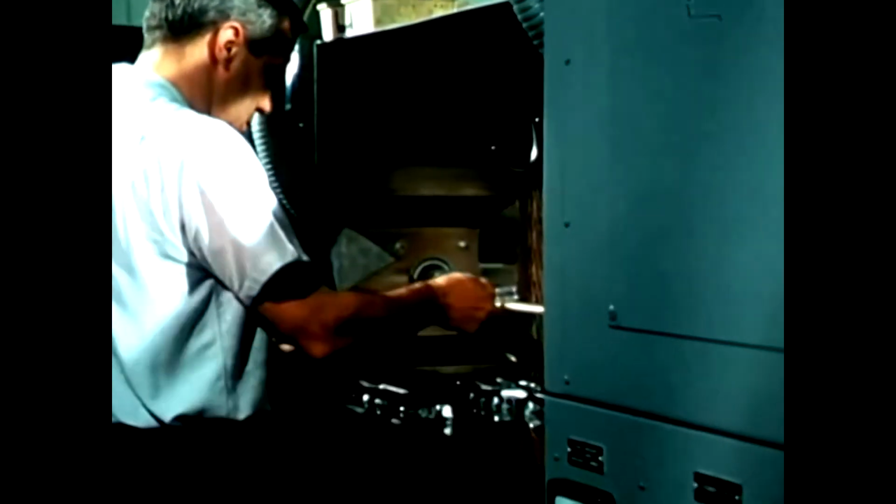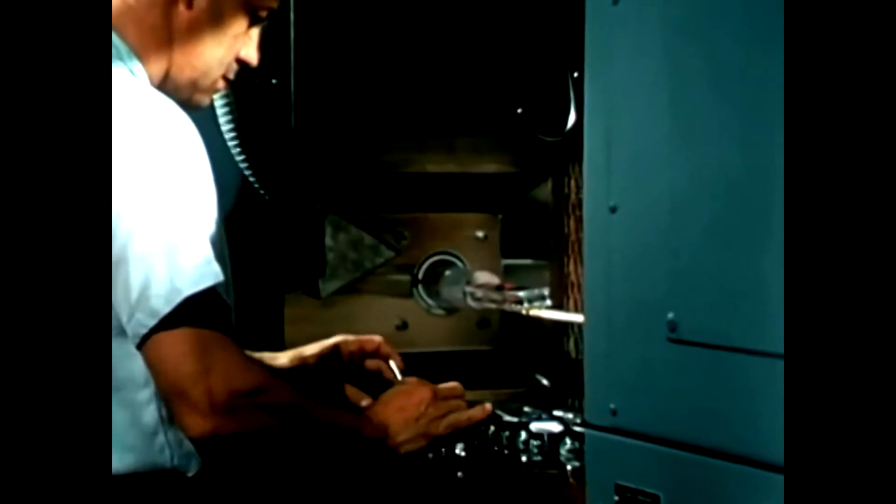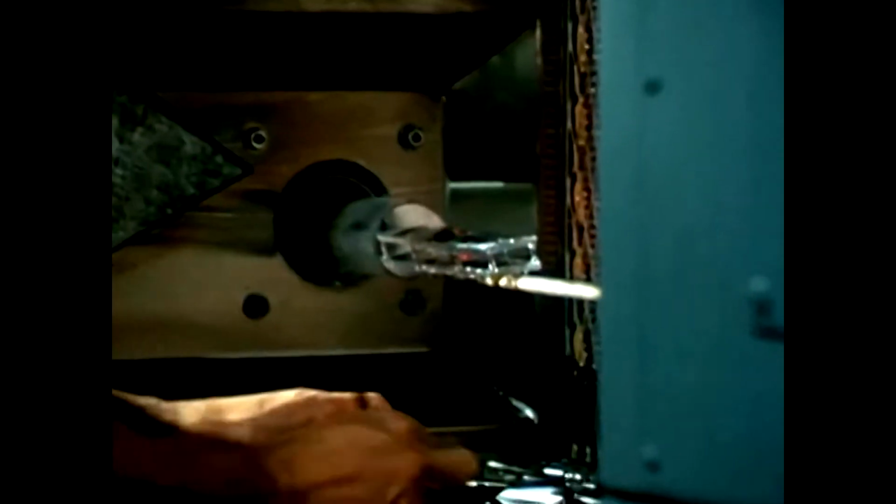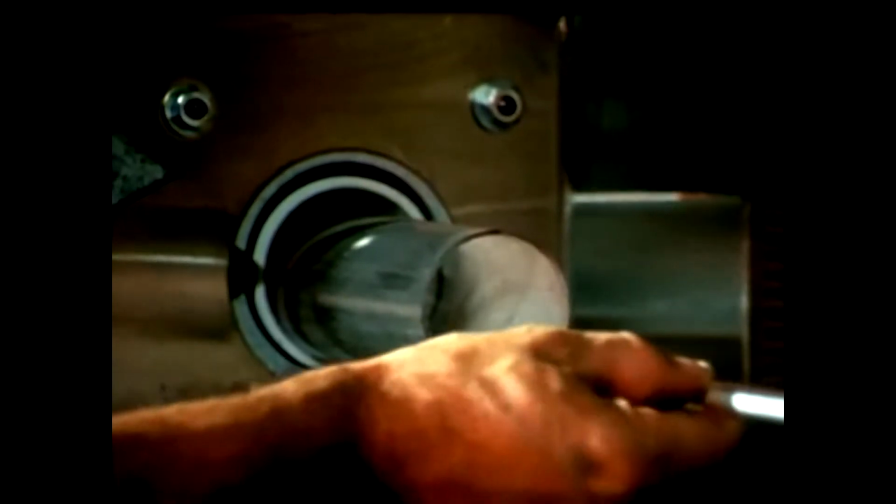Materials such as boron and phosphorus are diffused into the silicon to provide desired electronic characteristics. This diffusion is measured in parts per billion. Patterns are made by a photographic process and then micro-machined by chemical etching to produce nearly 1,700 transistors on each slice.